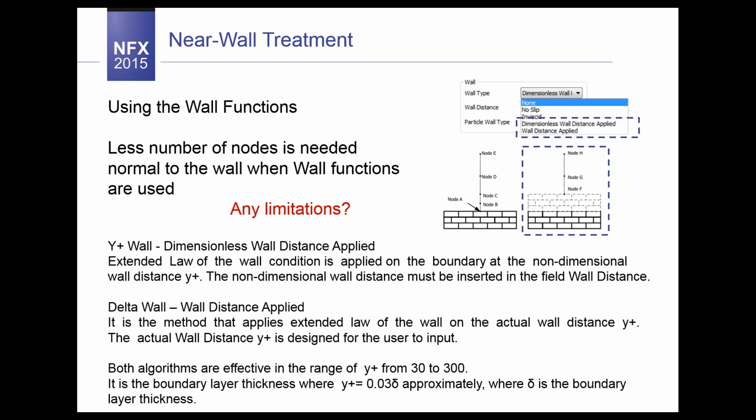This is one of the advantages of the wall function approach. If we consider the gradient of the shear layers close to the walls, all of them can be modeled with relatively coarse meshes. Which means we are using this approach to provide an empirical formula for this region close to the wall, let's say the wall of the pipe. Airfoil is maybe not a good example because it is related to external flow, so let's stay with internal flow. And after that, we still have to think about the proper distribution of the mesh. This time it can be less dense, but we have to do this manually.